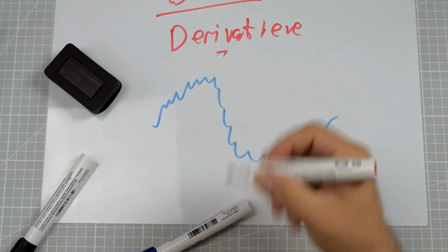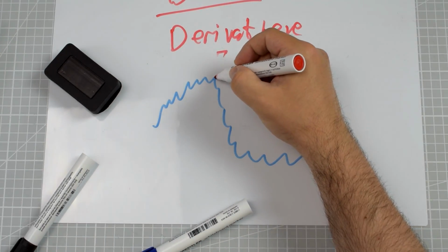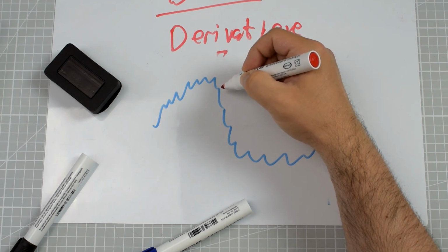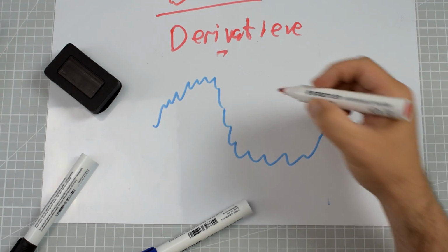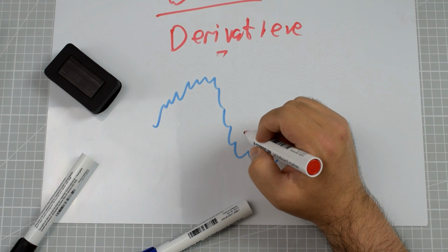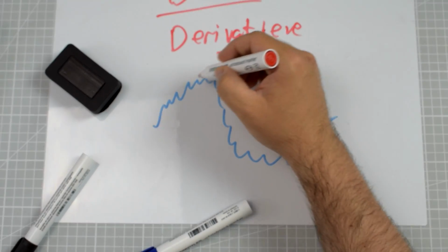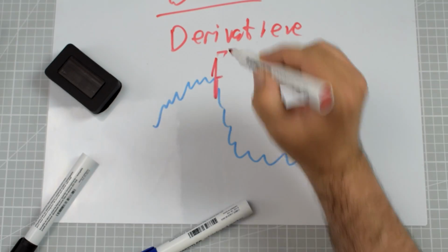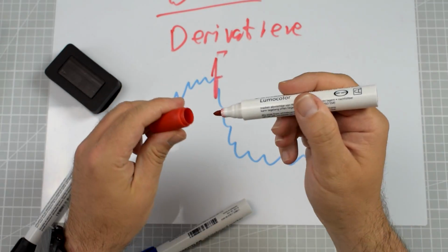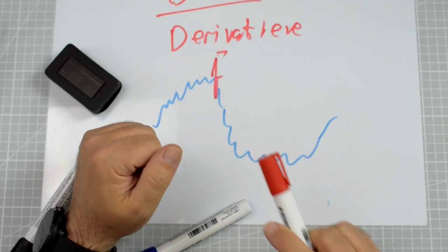Those small spikes over here are not really relevant for the gyro signal itself, because they have very low amplitude, but because they are happening very rapidly, the D term on such a change can have much higher amplitude, and this can be fed to the motor.